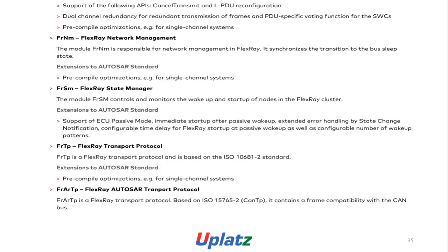FrSm, FlexRay state manager. The module FrSm controls and monitors the wake up and startup of nodes in the FlexRay cluster, an extension to the AUTOSAR standard. Supports ECU passive mode, immediate startup after passive wake up, extended error handling by state change notification, configurable time delay for FlexRay startup at passive wake up, as well as a configurable number of wake up patterns. FrTp, FlexRay transport protocol. FrTp is a FlexRay transport protocol based on the ISO 10681 standard, extended to the AUTOSAR standard, pre-compile optimization. Example, single channel system.